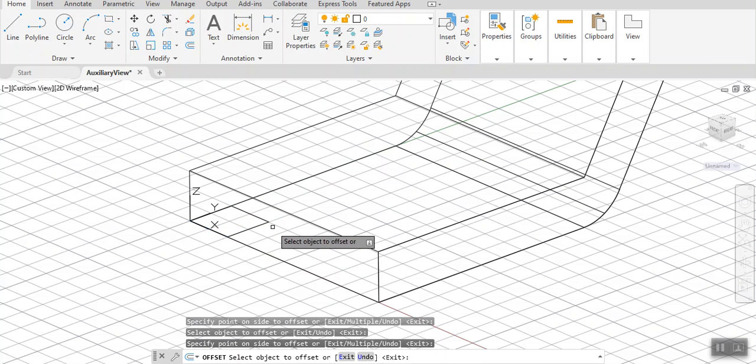So the intersection of these two lines indicates the starting point, okay, of my first cylinder. This is the center of the cylinder that I'm going to create. So that's why I created a 1 inch line here, 1 inch line here. I offset it this way. And then I created the XY plane on this base surface before I offset it. And then I offset it. Okay?